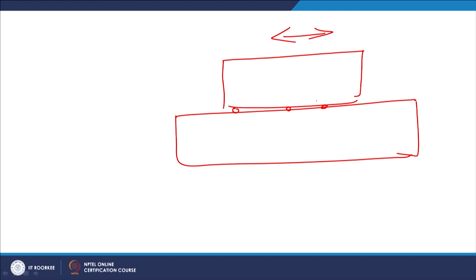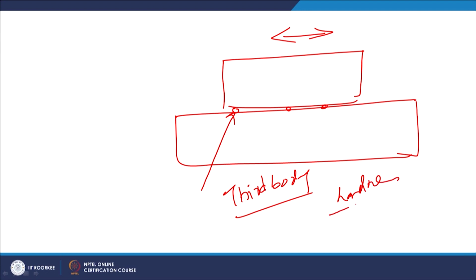These wear particles will remain for a while between the mating components and act as a third body. Most of these wear debris particles are harder than the respective base metals, because their hardness is increased by the work hardening effect.